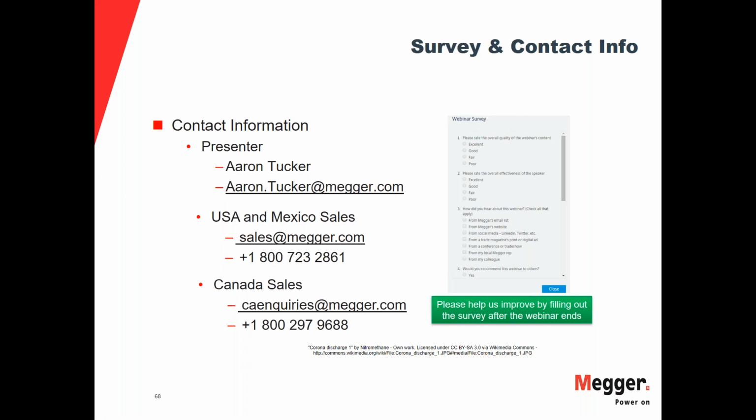So basically, just to summarize, the answer is, if the de-energized tap changer has not been exercised for several years, it does require some mechanical maintenance to be done. With that being said, when the mechanical maintenance has been done, you are safe to test it. If it's not, then you may get in trouble. So be aware of that.